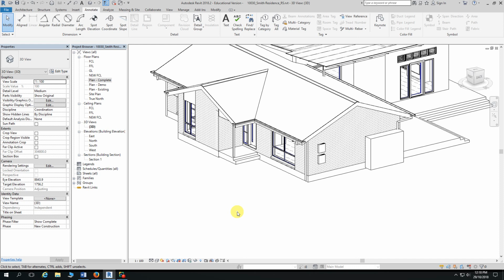One of the typical or most popular ways to do it is through the type properties, as we did with the wet area floor. Okay, you can assign materials through the category, so you can actually assign a material to the entire category, which you looked at in that assessment task. Now there is a third way of actually assigning a material to an object.